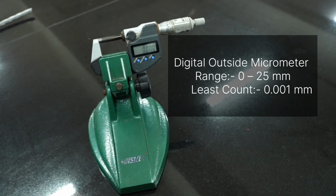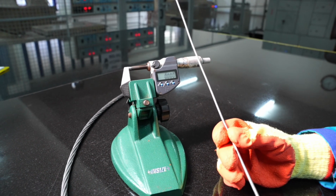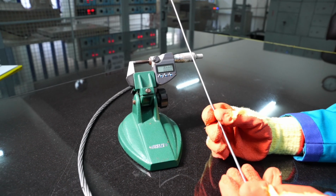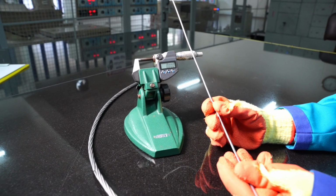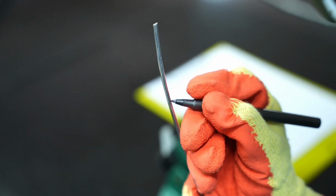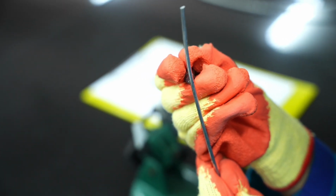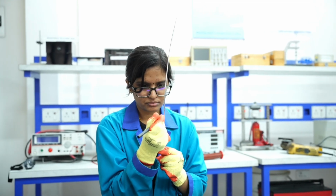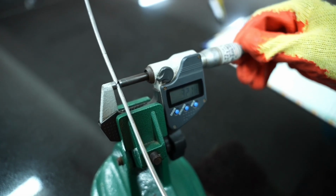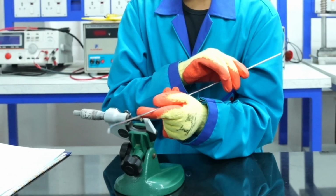Procedure: the nominal diameter of the sample taken up for testing is 3.15 mm. Ensure the sample is straight. Length of the sample required is approximately 1 meter taken from standard conductor. Mark the measurement points at random places at the center and at the two ends of the test specimen using marker. The diameter is the average of two measurements taken at right angles at the same cross section.